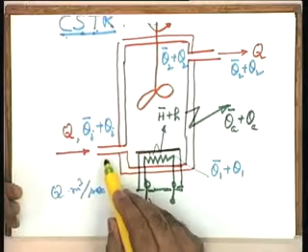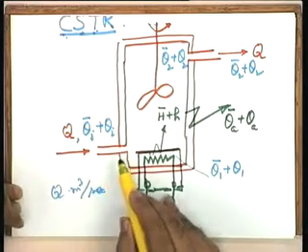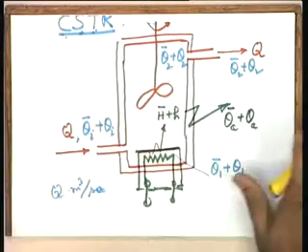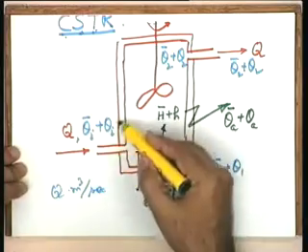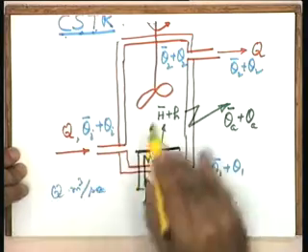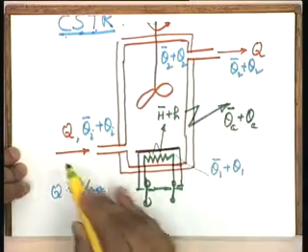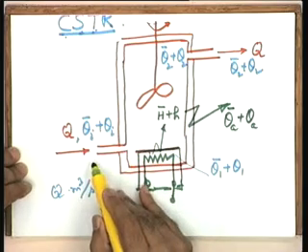The inlet or the inflowing liquid is also a source of heat, because any variation in the tank, you see at steady state certain amount of heat is going on along with this liquid, but if there is a variation in the temperature, naturally there will be a variation in the heat carried by this liquid, and therefore there is going to be a variation in the heat input to the tank through this particular source.